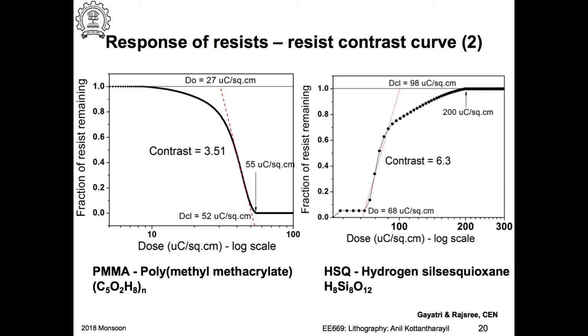Okay. So can you now tell me what would be, this is the position on the wafer. Okay, this would correspond to some features. So positive photoresist means wherever you expose it to light and you dip the whole thing in a developer, the resist will be removed. Okay. Now can you draw the profile, how the resist would look after development?